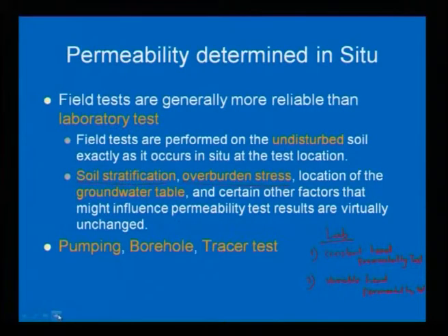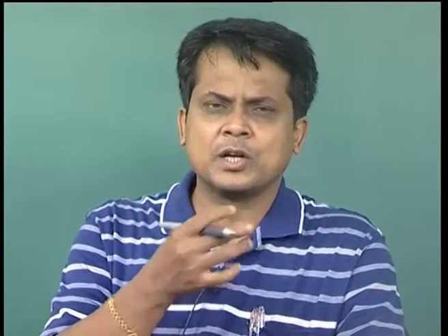These are the two tests we generally do in the laboratory. What tests do we generally do in the field? The pumping test. You pump a certain amount of water and allow it to flow inside the borehole, then measure how much time it takes to flow a certain amount of water.